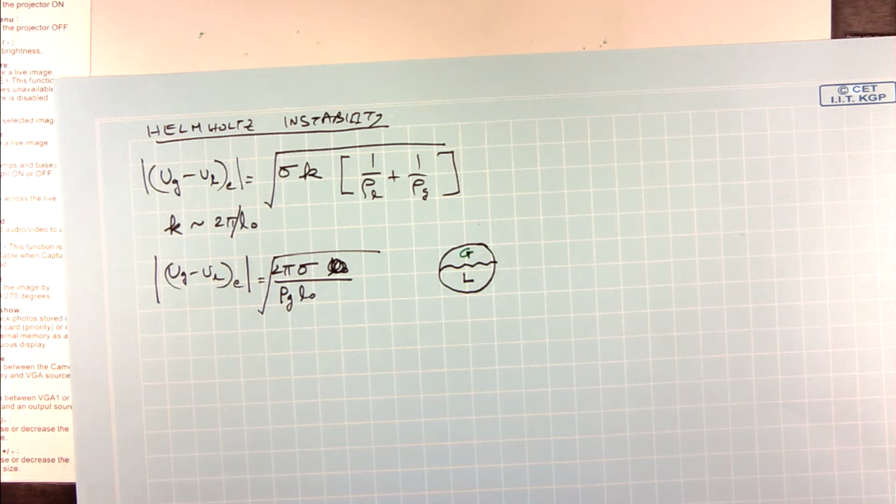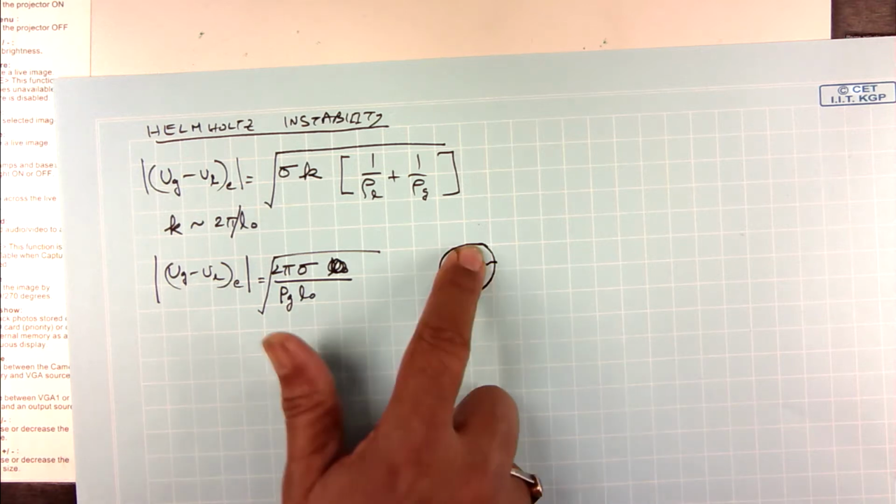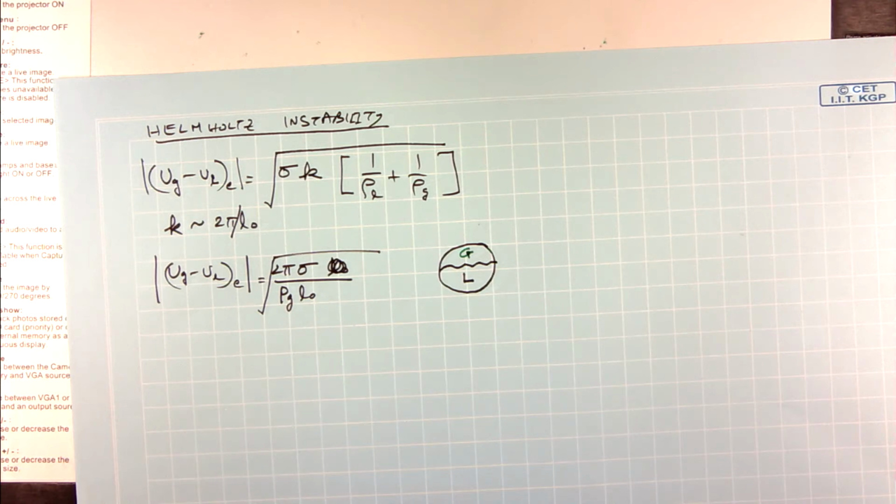And these are not pure, these are probably a mixture of different hydrocarbons. So, depending on the pressure, the concentration of the different components in the liquid and the gas will change, because the lower volatile materials might be more in the gas phase and less in the liquid phase, depending on the pressure and temperature conditions as the pressure drops along the pipeline. So, it is a very complicated problem, right.